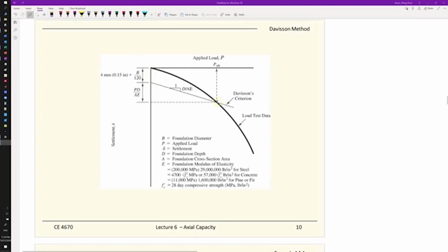Realize you try to pick a point kind of in the middle. So if you know ahead that your design will be everything related to displacement, you know that you're expecting large displacements, then you may want to use the values that represent that. Versus if you have a very small strain or small displacement pile behavior, then you may want to use a smaller displacement. So this Davisson method is nice as an approach to guide you how to pick a number, but you need to understand this. You're engineers, so you will make the call in the future.